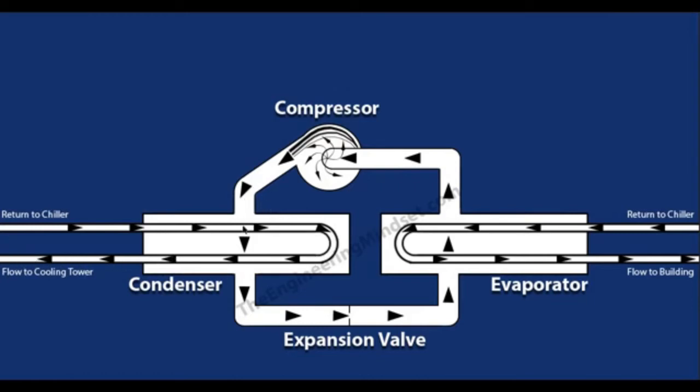The refrigerant comes in and condenses along the tube wall. It does not enter into the water. It just condenses on there and continues flowing through there, pushed by the static pressure until it hits the expansion valve. The expansion valve is just expanding that refrigerant, giving it a greater ability to pick up heat when it gets into the evaporator there. So these are the four main components and the three main circuits you need to know about. They will appear in every chiller, all types, sizes and shapes.